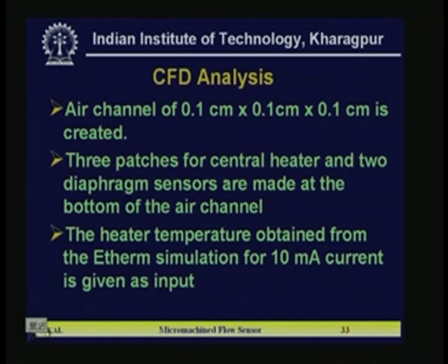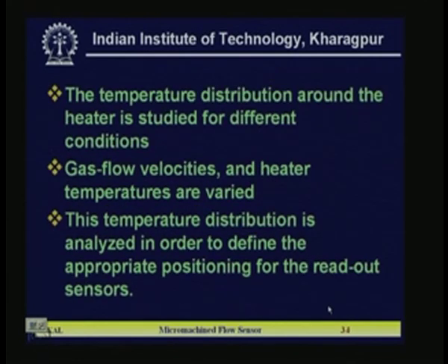3 patches for the central heater and 2 diaphragm sensors are made at the bottom of the air channel. The heater temperature obtained from the E-therm simulation for 10 milliampere current is given as the input for CFD. The temperature distribution around the heater is studied for different conditions. These are the steps for the simulation.